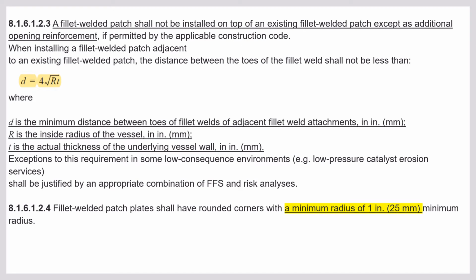For a fillet weld patch plate, there is a calculation which you need to remember. This calculation will come in open book and closed book, both. So, a fillet welded patch shall not be installed on top of an existing fillet welded patch. This is a closed book exam. Fillet welded plate is not installed on top of existing fillet welded plate except as additional opening reinforcement.